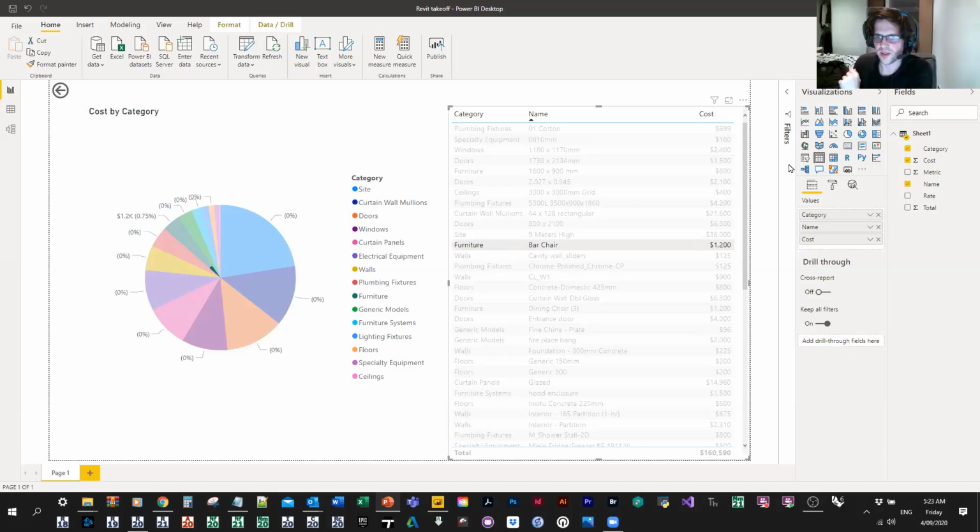That would replicate the cost data, but to conglomerate the 2 sections of cost together was what I was doing. I thought you were doing cost times count. Cost times count, yes. That was the issue, where you can't use the native count parameter in a formula in a calculated field. I've only worked around that in the past by introducing a native count parameter to the families themselves, and that supports a counting mechanism.